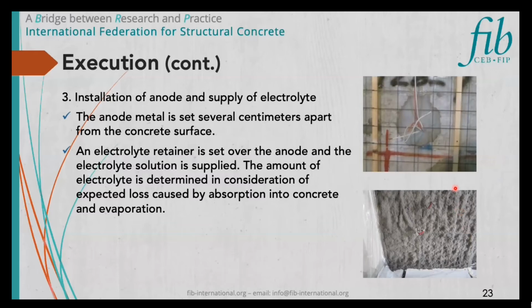Then, the anode is installed on the concrete surface. The anode metal is set several centimeters apart from the concrete surface. You can see that wood beams are used as spacers between the concrete and the anode mesh.